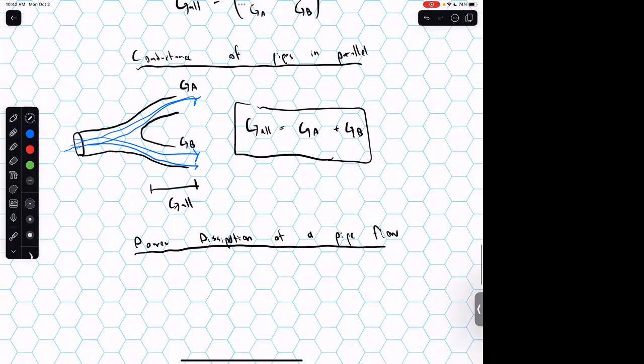Okay, so if I have some flow through some channel, and that flow has some rate Q, where again, Q is just volume per second. It's how many liters or how many meters cubed of oil I'm pumping per second. If that pipe has some geometric property, the conductance G, which is primarily set by geometry, it does depend a little bit on the viscosity, but usually that's just set by whatever fluid we're working with.